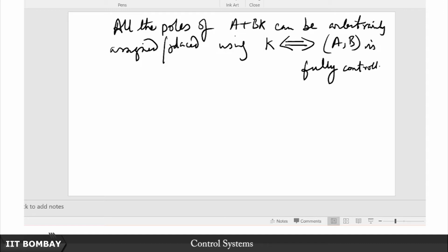Now you might notice something here, I am using this term fully controllable, not just controllable. You might say okay, just my fancy, I just popped it in here, but there is an implication to that. Unfortunately again I will have to use that excuse that this is an undergraduate course, so we will not be able to delve into the details of that. What I mean by fully controllable is just what we have termed as controllable so far, which is to say that the controllability matrix is of full rank, full row rank, or in our case because it is SISO, it is going to be invertible. So what if I am calling this fully controllable, does that mean that there is something called partially controllable?